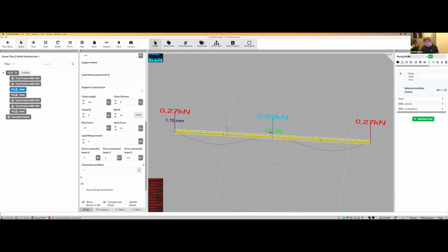So in practice, there are multiple ways of handling this. The first one is to level your grid, so that the assumptions are met. The other one is to use load measurement cells. When you're running a structural calculation for a big grid, you only know that there is one way that you can hang it with these forces, and you use a load measurement cell to actually reproduce this kind of calculation.